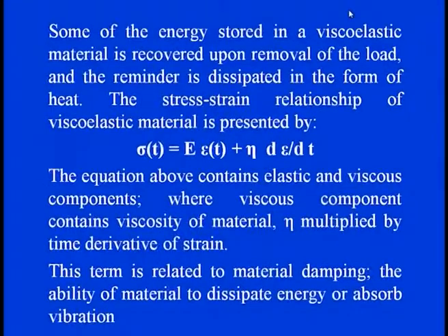So now we can add this feature to the stress strain relation for the viscoelastic material. Sigma of t, which was earlier, as the elastic material feature, E into epsilon of t. Now since the viscosity is also an important feature in the viscoelastic material, sigma of t is nothing but E into epsilon of t plus eta, the rate of strain, d epsilon by dt.